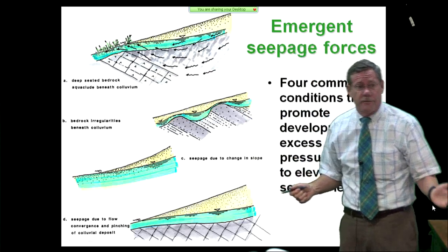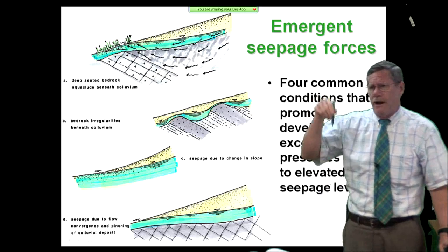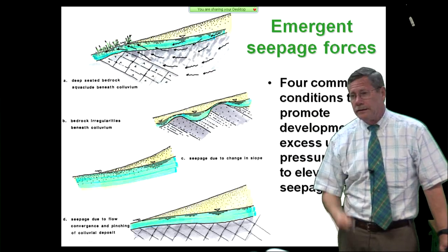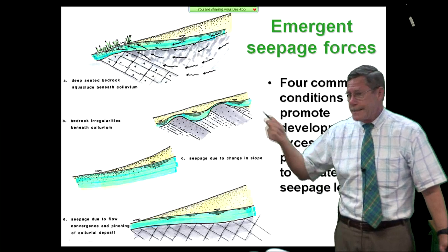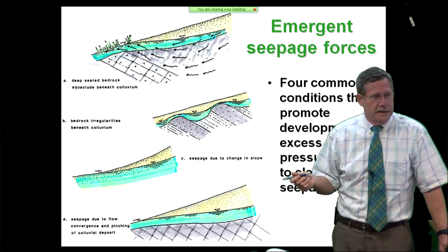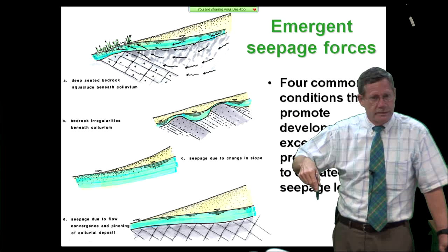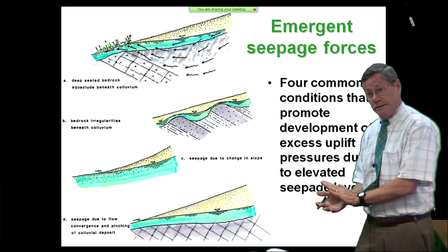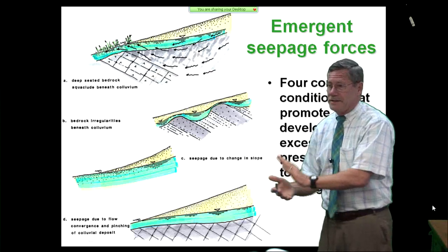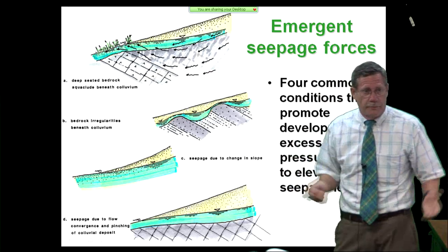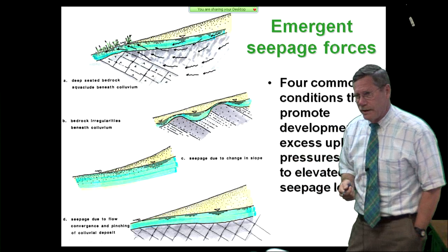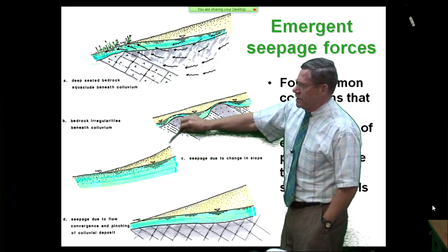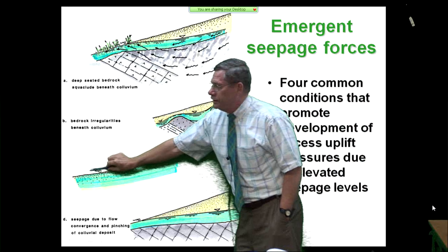We thought we had hit a fire main. But it went down rapidly. And within 3.5 hours, it was just dribbling out of the hole. And by the next day, there was nothing coming out of the hole. What we had done is, we had tapped the slide plane, the basal slide plane, and there was trapped pore water in that basal slide plane, and we alleviated the pore pressure through putting in a subdrain of sorts, the borehole.